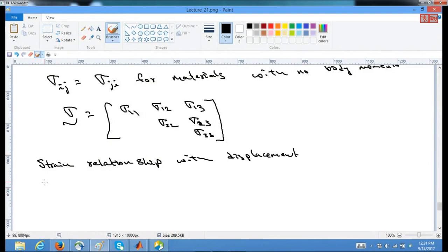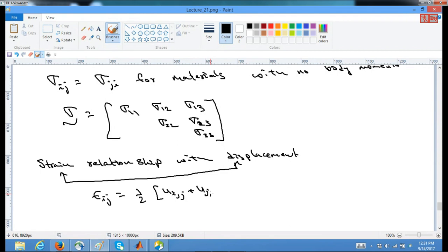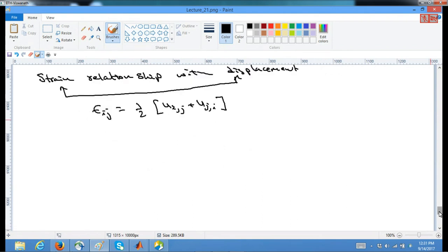We had your displacement. I will also bring the stress-strain relationship in a later slide, but let us see this relationship with the displacement in greater detail, which is nothing but epsilon ij equals 1 half (ui,j plus uj,i), with a greater look for a two-dimensional state for the finite element sense.